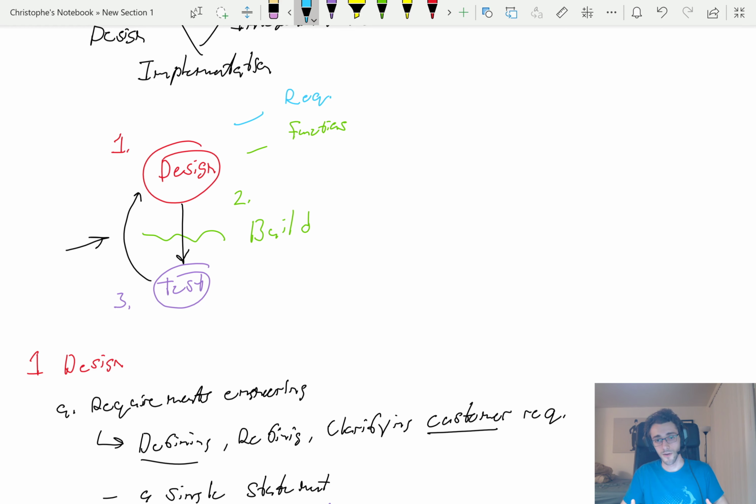All right, now what you want to do is start looking at your systems, your subsystems, your assemblies, and your components. So you go, okay, in order to perform these functions, we need A, we need B, we need C, we need D. How do these systems, subsystems, assemblies, and components break down into one another? So you're going to be starting to look at the components tree. I say components, I really just should label this as systems, but for continuity, I'm just going to say components, because it's looking at the physical architecture of your system.